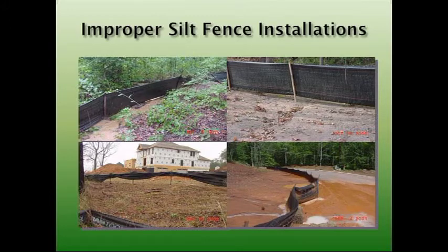These are pictures of improper silt fences. Like I said, you see the gaps here. You see it getting out in the street here. This one, I don't know what they're doing.